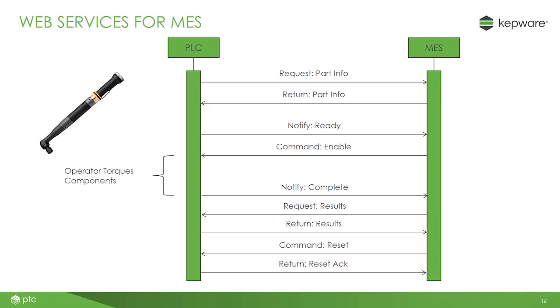Now, as a demonstration, what we're going to do is I'm going to use a couple tools from Node-RED to basically mimic one of the scenarios that they do within their manufacturing lines by monitoring and executing to one of their processes to access data from torque tool devices through a PLC and be able to do that exchange, deterministic exchange to verify that the data is correct, to verify their process was executed correctly, store the data, and then be able to release the line to move on to the next component.